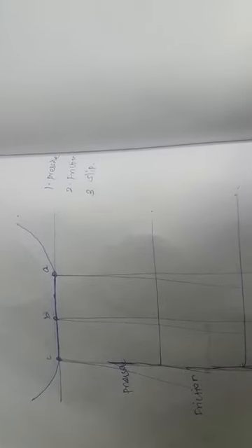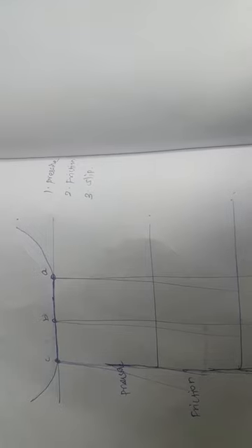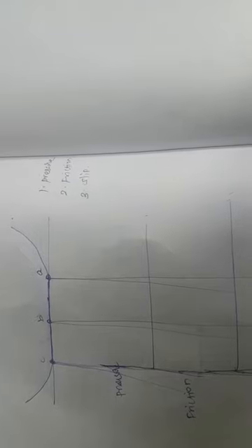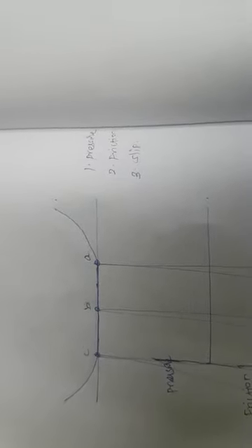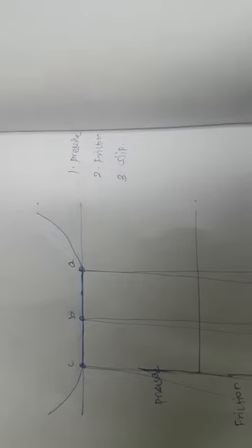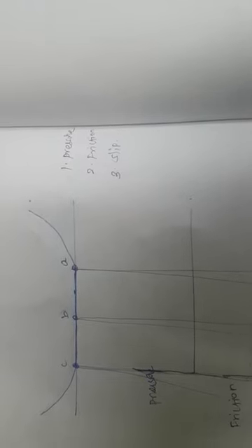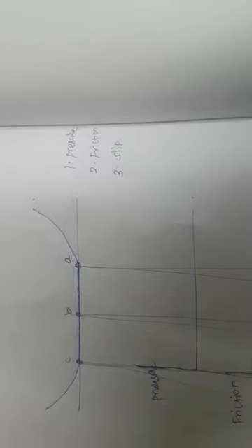As the tread elements first enter the contact patch, they cannot develop a friction force because of their compliance. I repeat, the leading point elements first enter the contact patch. They cannot develop a friction force because of their compliance. That is a property of elastomer, a viscoelastic material property, right?